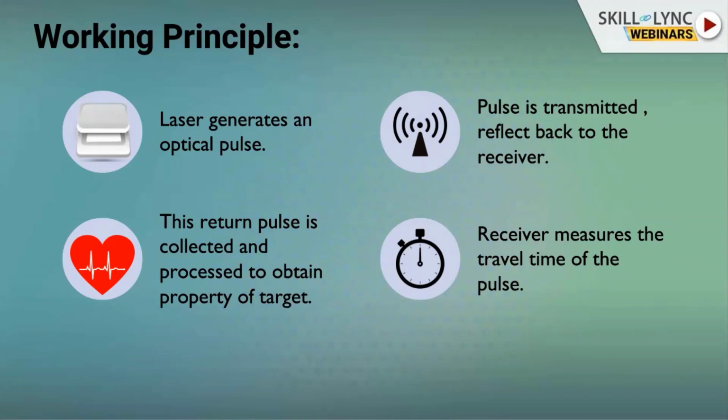When we transmit our light rays, like UV light or infrared light, whatever bandwidth is there, after hitting an object, like the car in front of you or any object through which the laser beam cannot pass, some light will reflect back, some light will be transmitted, some light will get diverged in the medium itself, but we only have to focus on what reflects back.